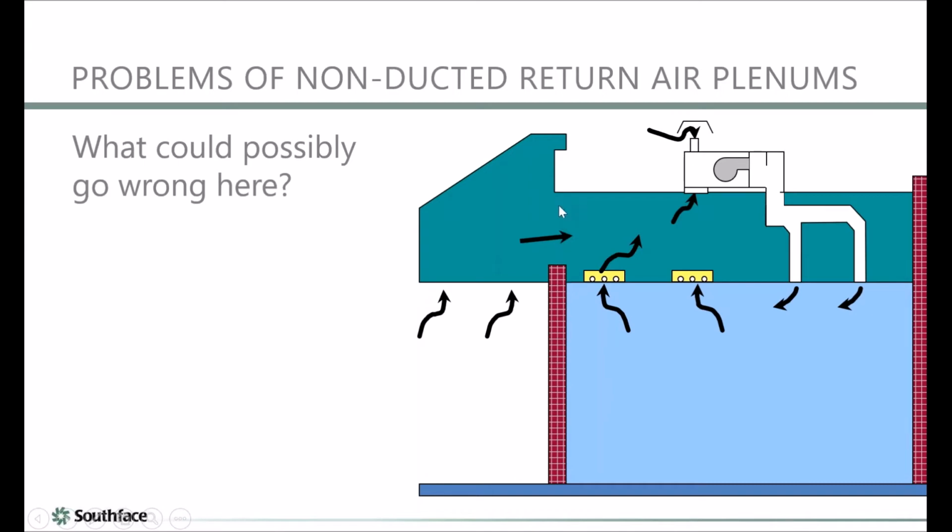No. The plenum in this case was inadvertently extended out to include this big overhang. And it's very common in a commercial building. I personally have found this in multiple buildings. Whenever there's an attached tuck under, a porte-cochere like a motel might have, or the entryway of a building, very commonly this wall stops just above the visual line.